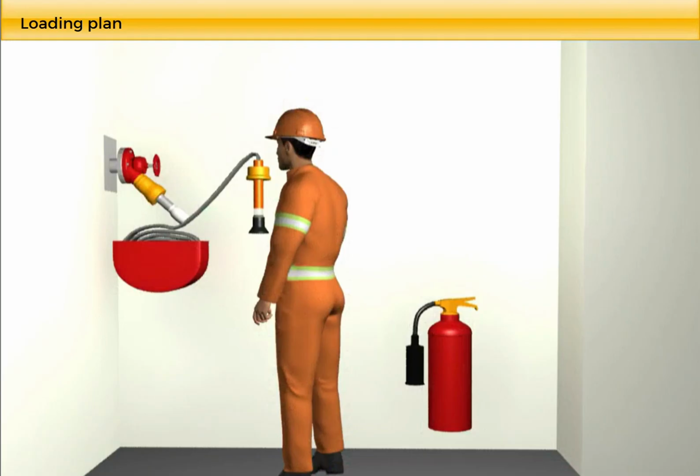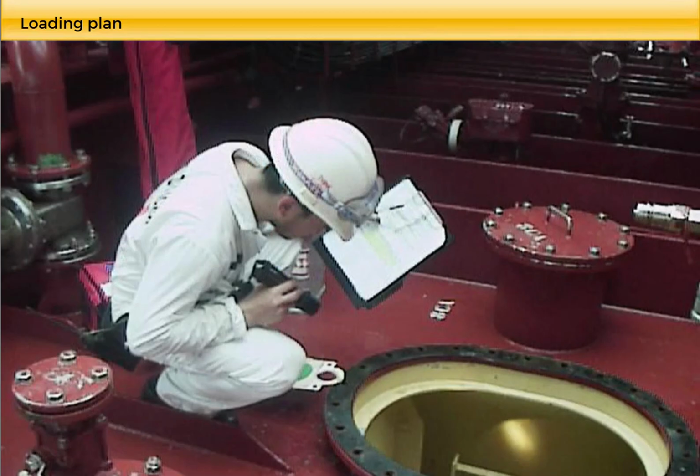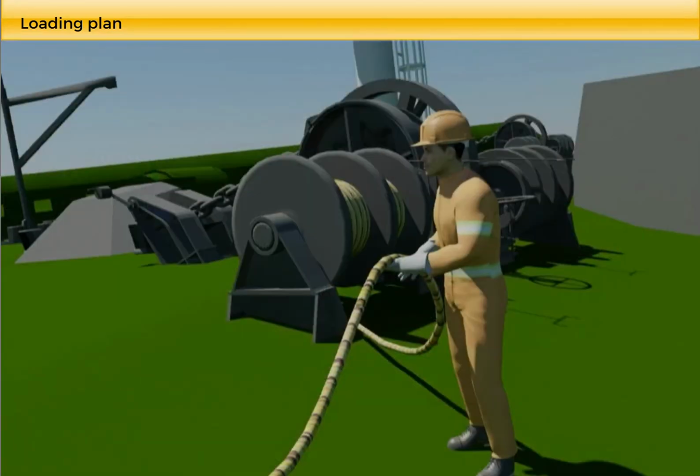The junior deck officers are responsible for checking their designated equipment and systems, such as firefighting and life-saving equipment, navigational instrumentation, etc. The pumpman is responsible for function checking of all cargo-related safety systems and equipment. The boatswain with the deck crew must check and prepare all mooring equipment, oil pollution prevention equipment, accommodation ladders, pilot ladders, hose handling cranes and deck scuppers, and assist the pumpman with preparation of the cargo manifolds to be used.